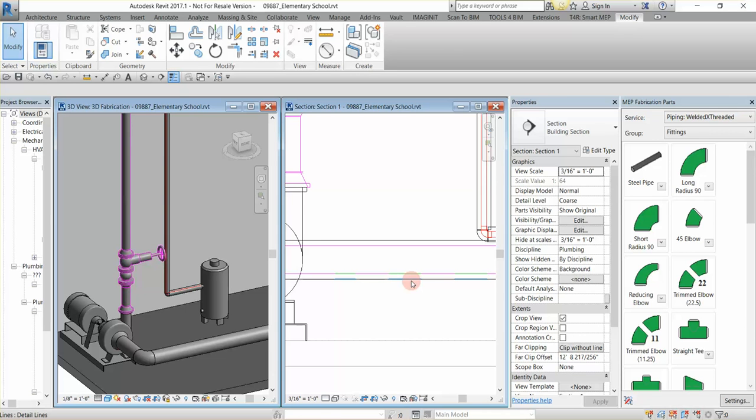Now we would potentially look to expand that because obviously those size rules change based upon the temperature in the pipe and things like that. So if we were doing steam or steam condensate or domestic hot water lines, that thickness range is going to be different based upon whatever we're trying to follow, whether it's ASHRAE tables or anything like that. So let's take a look at how we can decipher that insulation, and then also maybe we just want to add some standard insulations that are not doing the automatic sizing for us, but more of just an assignment of, hey, I want 1/2 inch, or I want 1 inch, or I want 1.5 inches. So we'll go ahead and take a look at that.